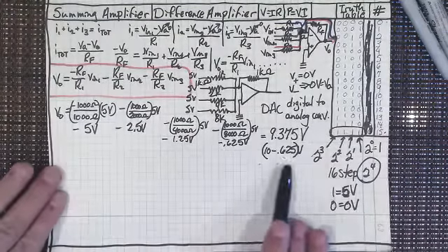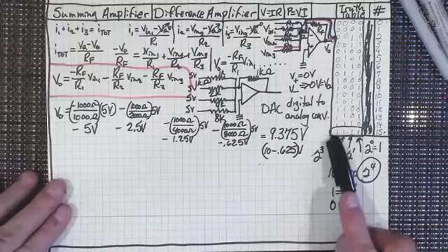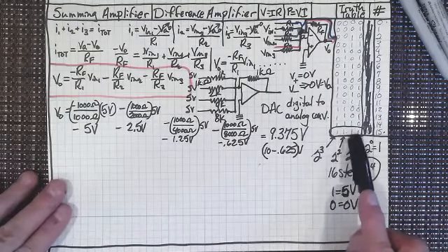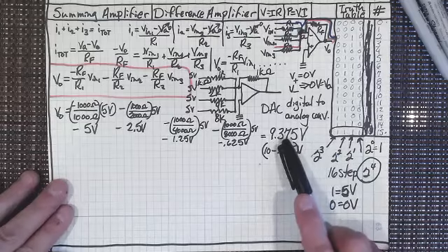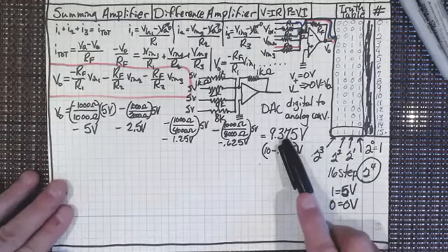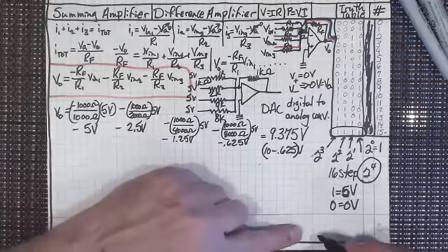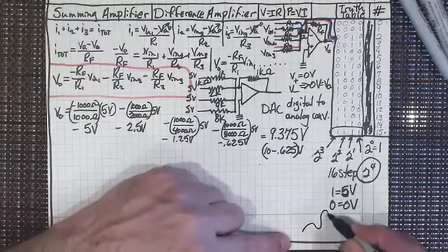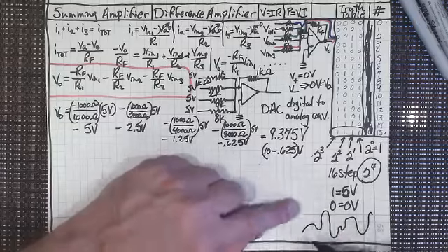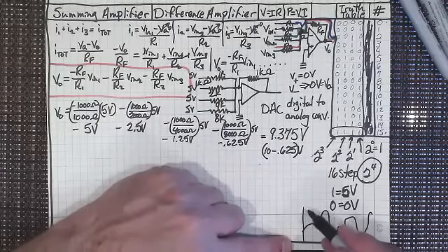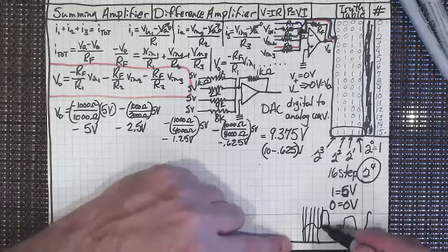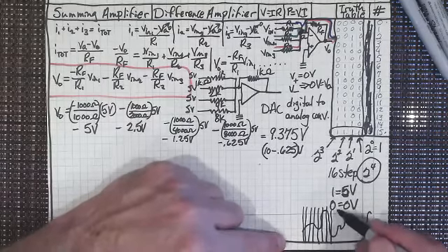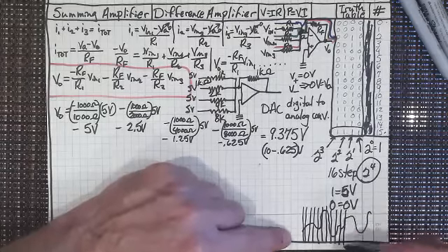Now, that's an analog. What we're saying is this binary string has just come into your audio player, right? It's being turned into a voltage so that you can hear it. That's how we do it. We digitize audio signals. So let's say I've got an audio signal that looks like this. What I do is I take slices of it. I sample that audio at various different places so that I can find out what the voltage level is and lay that down in my digital track that I've got here.